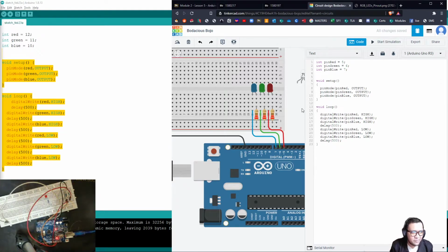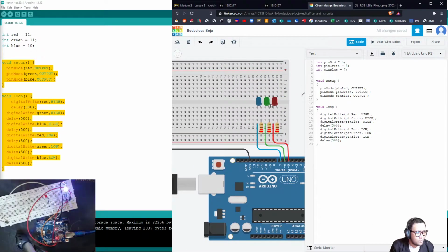Diodes, specifically LED and other types of diodes, are very particular in the direction of the current. Diodes only accept current or electricity one way. Meaning, if you oriented your wires wrong, it will not turn on. So, let's try switching up the wires.